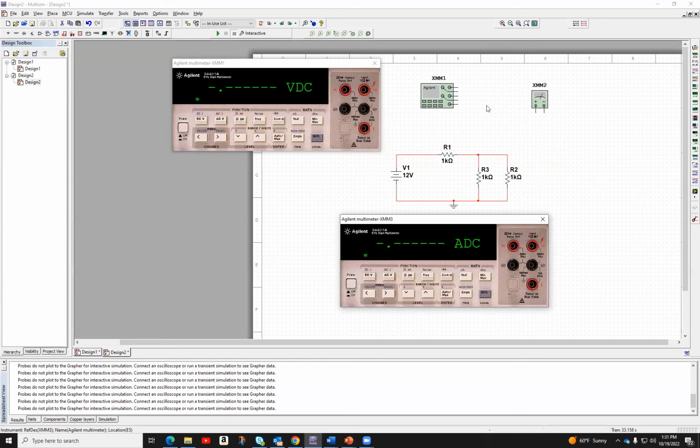If I want to measure voltage with this one, I'm going to go from here. So I want to measure the voltage across these resistors, resistor R1. Oops, I made that. This is nice because it tells you this is wrong, right? You don't want to. You want to be between the red and the black. So actually, I need this one here. Okay, so this is now set up to measure voltage, right?